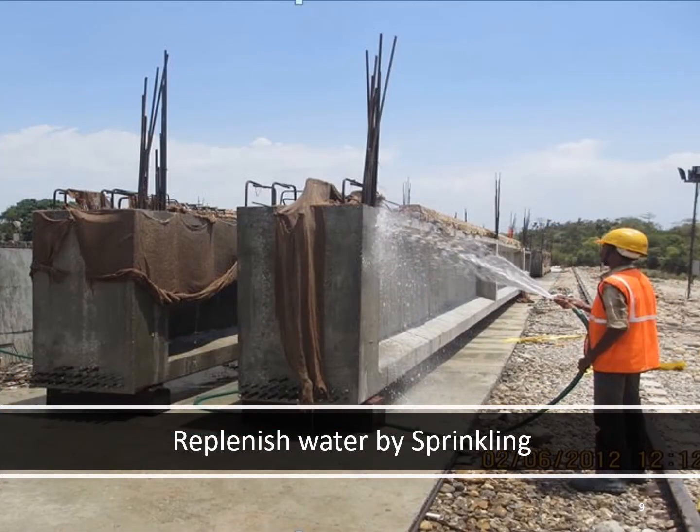So this is the basic sprinkling on vertical faces. Generally on vertical faces you can use wet Hessian cloth and then sprinkle the water on top of the wet Hessian cloth, so that the loss of water from the Hessian cloth is reduced, and you have some cover as far as the loss of moisture is concerned.